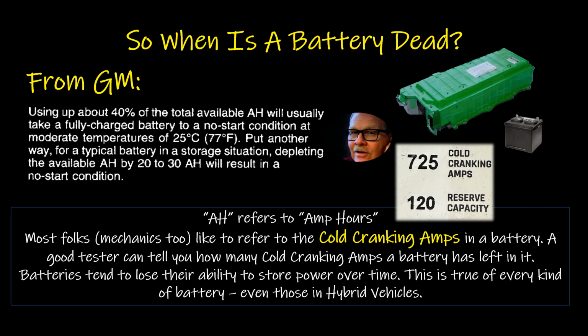Now, what you can do, if you can disable the fuel and the ignition system, well, you can actually just disable the fuel system really, and get it where it'll spin over but won't start, because you don't want it squirting fuel in there. So just killing the coil is not going to do this. So what you're going to do is have it where you can spin it over. And you can push the gas pedal all the way to the floor. On a lot of vehicles, it will be in clear flood mode.